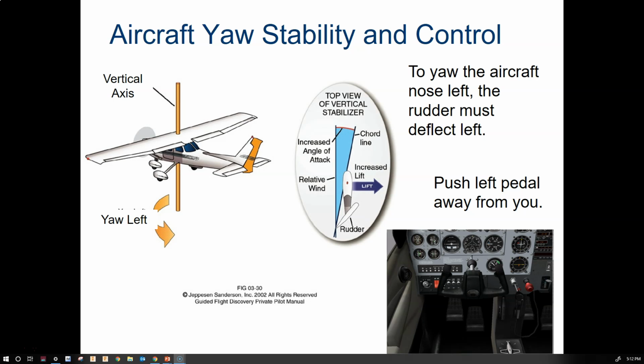When an airplane banks or rolls on the longitudinal axis, there's slippage that occurs. This is known as side slip. In a side slip, the airplane's longitudinal axis remains parallel to the flight path. The steeper the bank, the greater the degree of slip. As bank angle is increased, additional opposite rudder is required to prevent further turning.